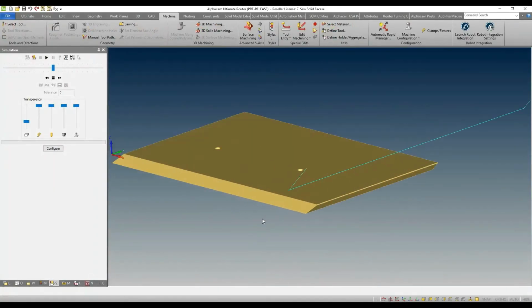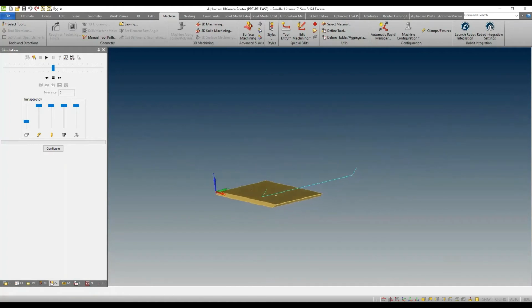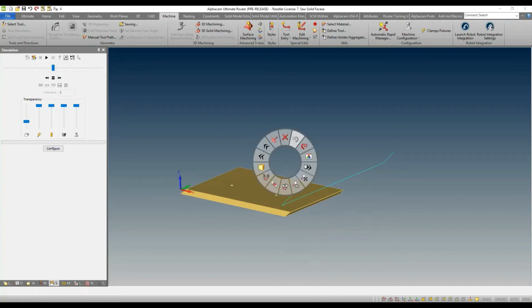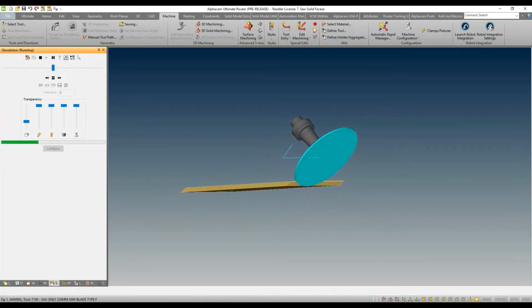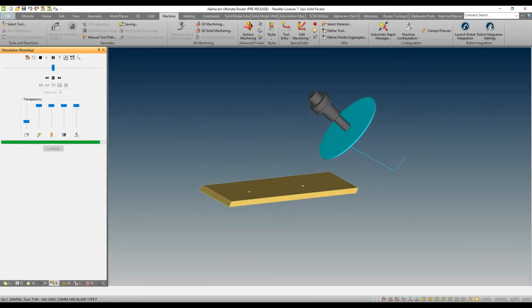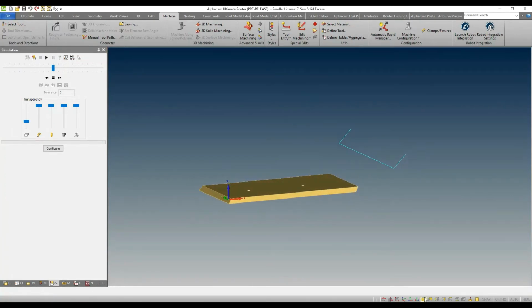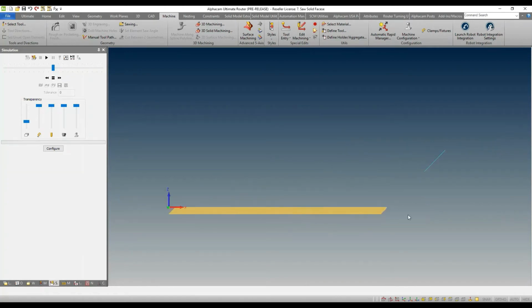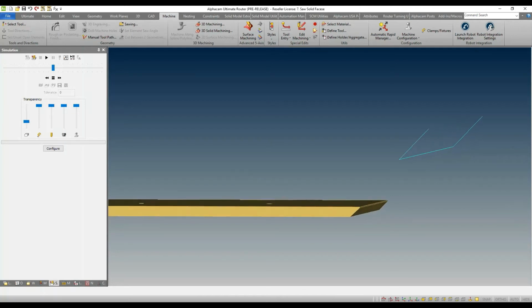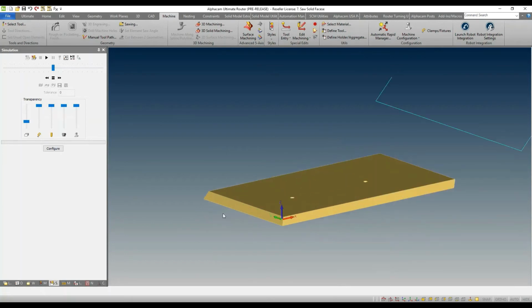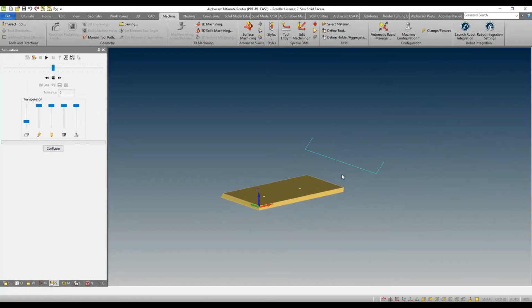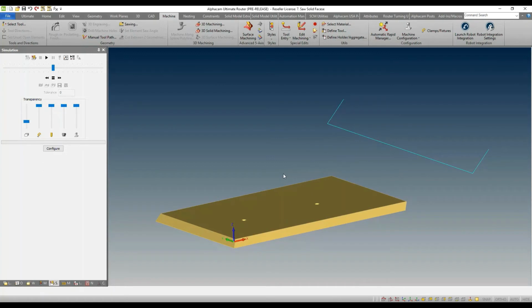The second enhancement that I want to talk about is the ability to saw solid model faces directly. You'll be able to see, for example, in our existing simulation, what is the intended application. I want to use a saw, and I simply want to cut the face of a solid. Now, in the past, you needed to know several things about this solid. For example, the thickness, you needed to know the angle, you needed to know, for example, the start and end point sometimes. In other words, there was a little bit of work involved in being able to do this complex 3 plus 2 machining operation.